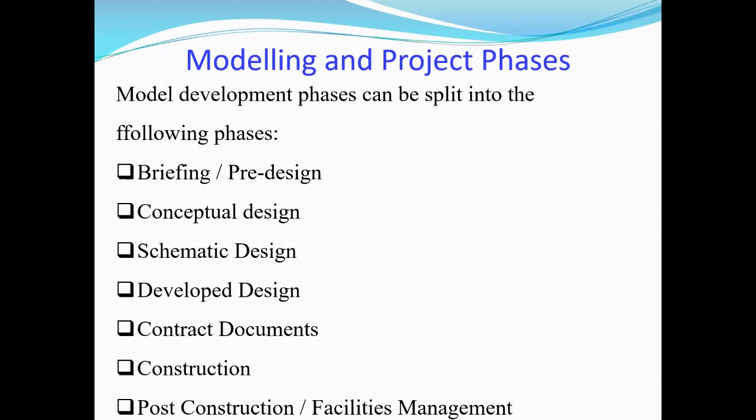At the schematic stage, generally we don't do any analysis. Based on our experience and knowledge, we do the size-up. Generally, we don't use analysis for structural member sizing unless the structure is very complicated. Then we do a very simplified analysis, 2D analysis or simplified 3D analysis.